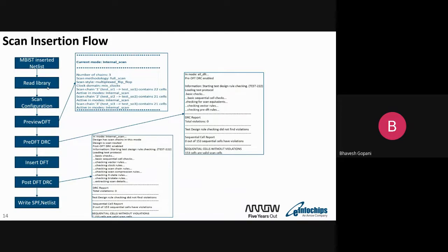So normally during synthesis, everything, logic is replaced. So certain checks need to be done during synthesis, because the same library we are using here also. Whatever library is used during the synthesis, the same library I need to use here. It has standard cell information of all the cells, like an inverter cell, all the different logic cells.